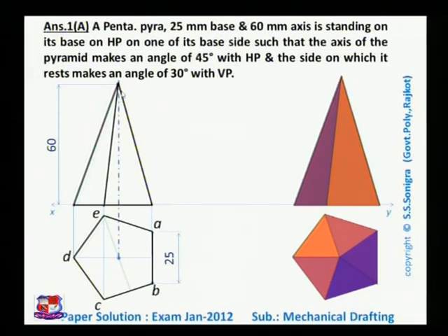So this is the triangle which represents the front view of the given pyramid. This edge OE represents the slant edge. Join them with a straight line because OC would be visible to us, OE will not be visible. Hence here two lines are there, one is a full line and another is a dotted line. So here the dotted line is to be covered by the full line because precedence should be given to the full line. This is apex point O. Join apex point O with A dash, B dash, here C dash and E dash points are there, and here point D dash is there.